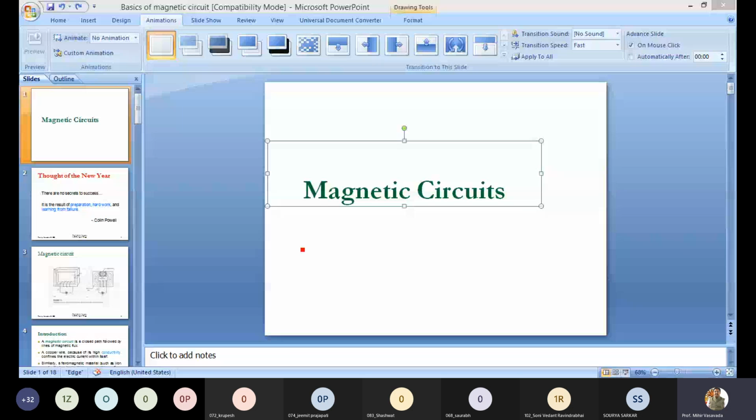So actually there are two types of magnets, natural magnet and electromagnet. If we talk about an electromagnet in a magnetic circuit, then the value of MMF produced by it is proportional to the product of current and number of turns. So the unit is ampere turns, AT, right? Generally turns do not have any units. For dimensional analysis, it is amperes, right?